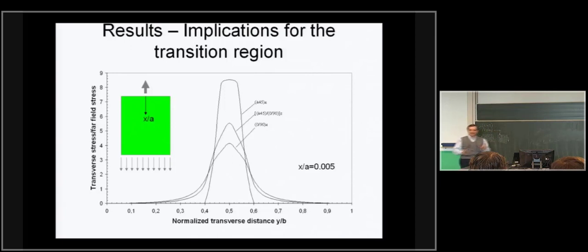So unless you really want to optimize the reinforcement and make it have the widest size at x over a equals 0 at the top, and then as you move away from that edge, it becomes narrower and narrower to follow the stresses reducing, you can do that. It's just much more costly, but it's also the most efficient if you are trying to reduce weight.